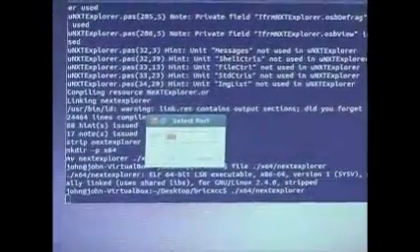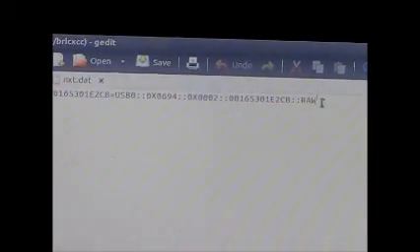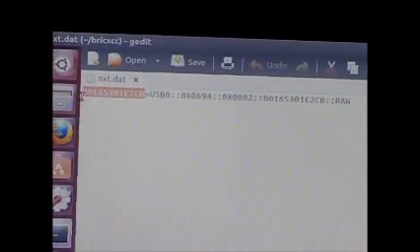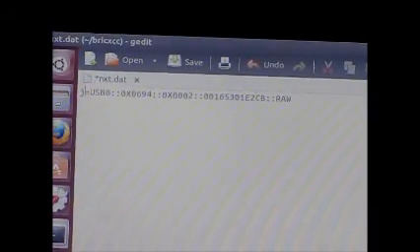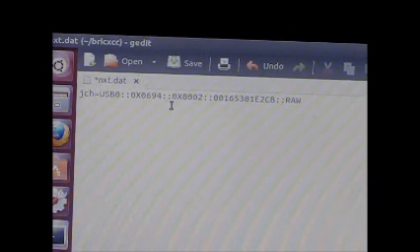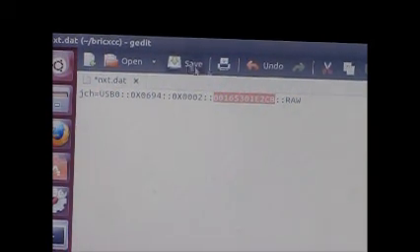Just really quickly, let me show you where you can find that file. It lives in your home folder, in the BRICS folder, in this nxt.dat file, and you can create it with the NXT tool utility that we talked about previously. If you tell it to -init, it will create or replace the contents of this file with any brick that it finds, and you can rename this to whatever you want. Alright, so JCH is now my brick with this serial number. So this is the key to which brick you're talking about. Go ahead and save that.